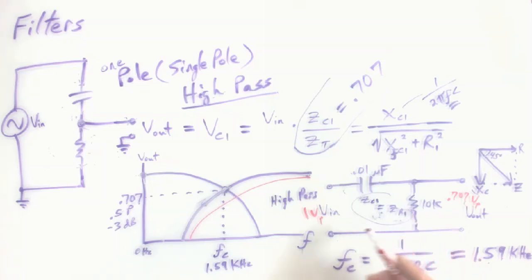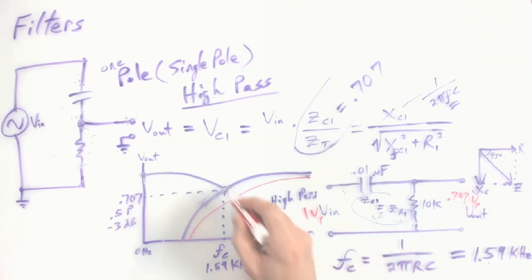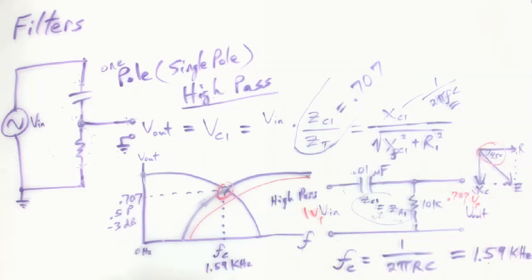You will also see on your scope screen that as you change the frequency, there will be a phase angle change that occurs between the input and the output. And in fact, another indicator that you've got to the cutoff frequency, I think we'll see 45 degrees between the input and the output. We might have to double check that, but it's going to make sense. We have to think about what we're looking at. Don't worry about that. I just kind of mentioned that parenthetically.